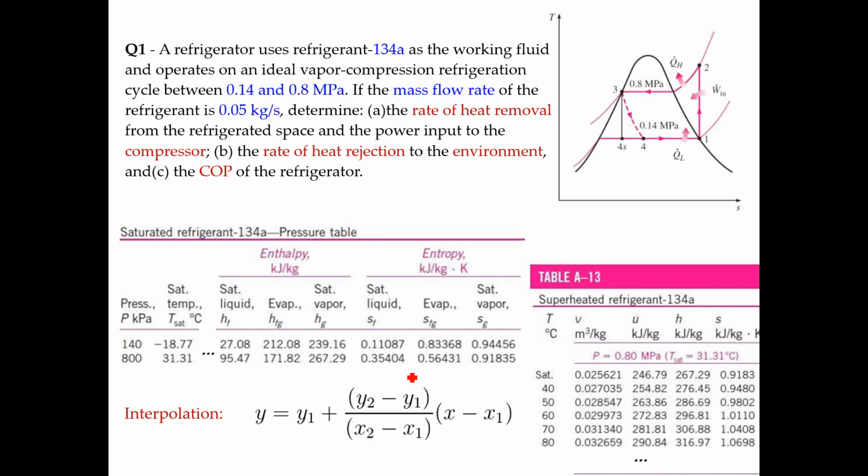Okay, so that's the first one. I didn't have the tutorial handout on this laptop, so I'm just showing you my printed one. This is the tutorial handout. If you go to the pages after week 2, you will see the tables of thermodynamic properties of saturated refrigerants, and later also superheated refrigerant. And you should have subcooled refrigerant, but that is a very long table. For example, in this textbook, we didn't provide the subcooled one. That's why in the second practice, we want you to practice on the pH diagram, because on that diagram you can read the values for the subcooled state, but you cannot find them from tables, because the tables don't give you that.